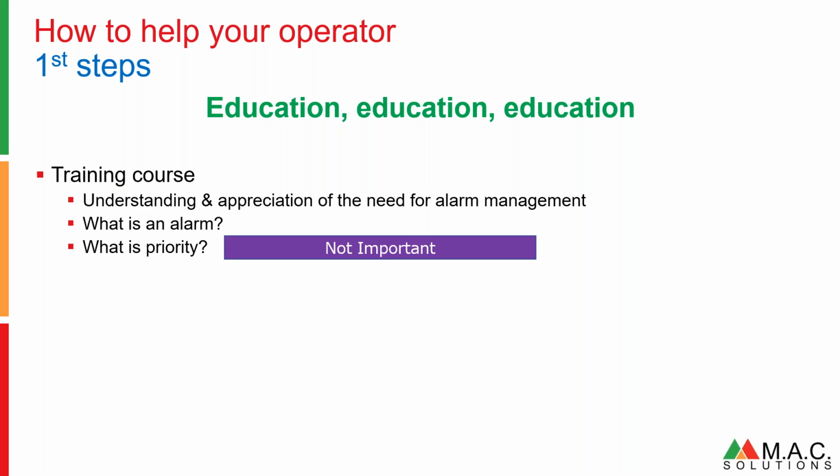I said, well, what's purple? I don't know. We've never been shown how to use this system. 2 or 3 years ago, they moved the control room from over there to in here, and we got this system, and we've not been told how to use it. We just do things. I said, so what is purple? We don't know. I delved around as part of my assessment, and I found manuals, and purple was actually a plant critical alarm. This was from a high integrity pressure system.